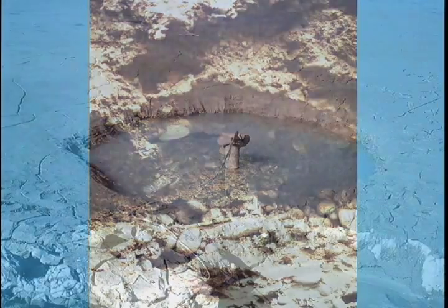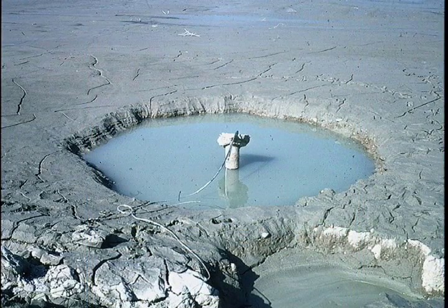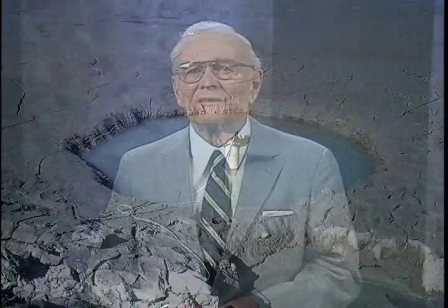This is a photograph of a sinkhole which developed in the material surrounding the casing of an instrumentation drill hole. Apparently, the installation of the casing disturbed and loosened the surrounding blanket material, making it susceptible to leaching out of fines from the blanket.